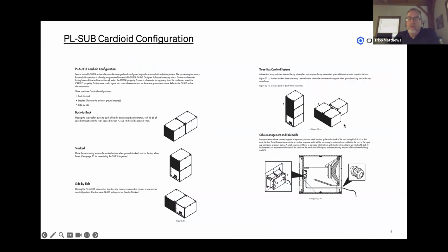When you get over to doing multiple drivers, one thing I will tell you is we've voiced this and powered this so that you don't notice a major loss in energy out the front, even though you are subtracting about 15 dB off the back. The voicing and development engineering did their best to keep that as smooth as they could. Generally, people have found that they need twice as many drivers forward as they need back to keep the LF in the room. Hence the images you see on the side over here, where you got 2 forward and one back, 2 forward this way with just one kind of hanging behind it.